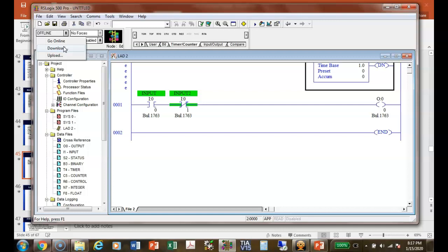If I upload a program, and it's backwards, by the way, from computers. So normally these two guys are computers, and this guy thinks he's the boss. So when we send information to the PLC, it's called download. When we get information from the PLC, it's called upload. So it's just opposite of what we see, right? When you're on the internet, your computer's the boss. PLCs, this guy thinks it's the what? It's the boss. So it's opposite. So sending a program to the PLC, we call it download.